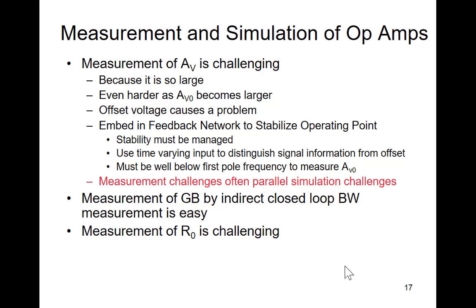So if I put a 1 milliohm resistor in, the output voltage should drop a factor of 2, right? So adjust this. Maybe I can have an adjustable resistor, and when this resistor causes the voltage drop to a factor of 2 from what it was open loop, then this resistor would be the output impedance of this structure. Right? That's commonly used to measure output impedance. Put a resistor on, adjust the resistor until the voltage drops to a factor of 2, then whatever that resistor is, that's the output impedance. What's wrong with that approach?